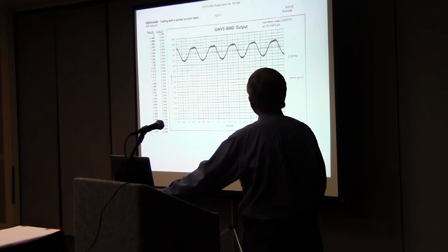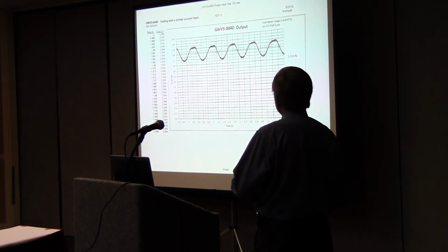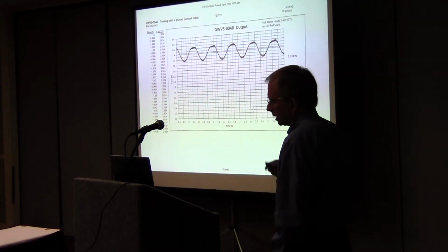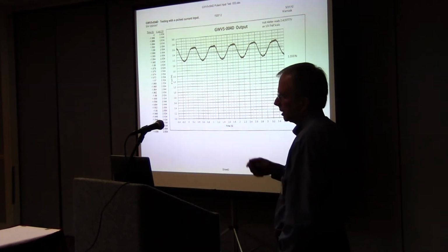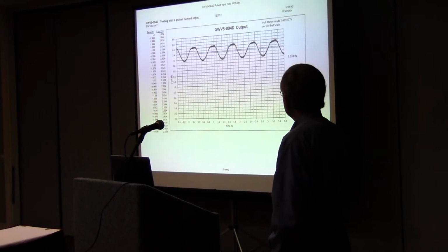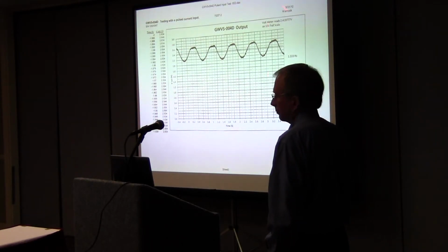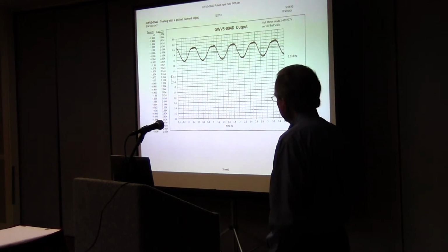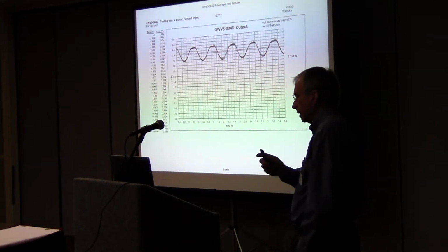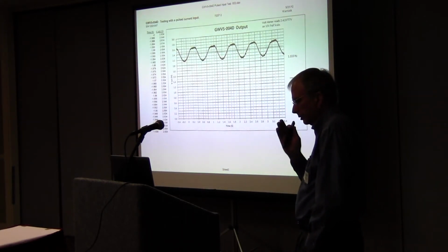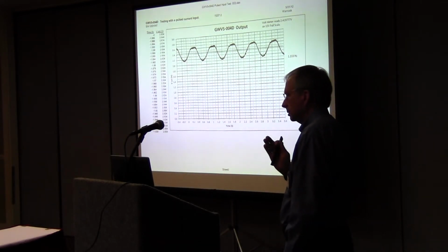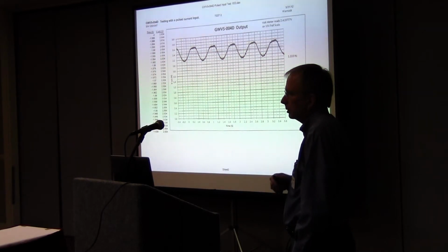Our GW5, this is actually a watt bar unit that had a little different sampling rate because we were doing watts and bars in the same transducer. But again, we got this beat frequency. And we were able to correct that by moving the internal frequency in our transducer away from the harmonics of 60 hertz. That's basically what we did.